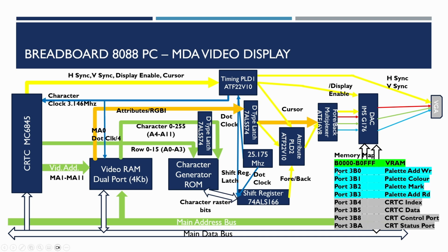Now, what this means is that in the video section of the BIOS, we'll need to initialize these and put some basic palette information in here as part of the BIOS. As long as programs are making use of BIOS calls to do this, it shouldn't actually cause any compatibility issues. These registers are generally not used within the address map, from my understanding.